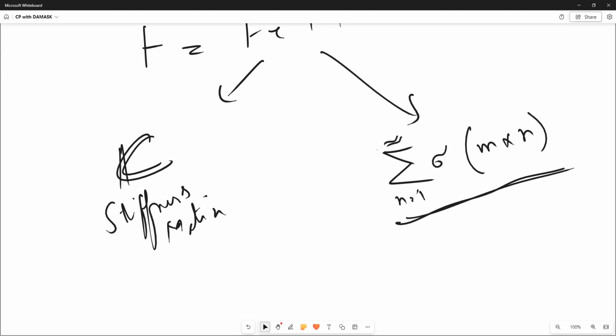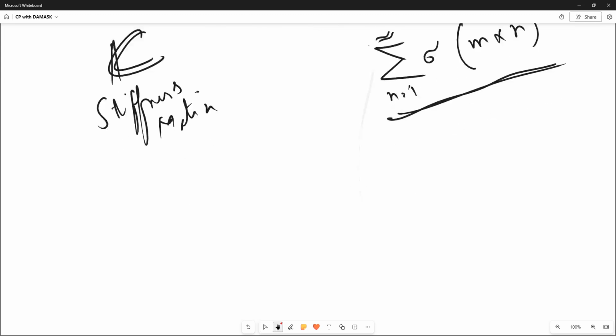And this is basically what we are trying to do, run or simulate using any crystal plasticity software. Here we are taking the example of, for example, DAMASK. You can use Abaqus with your own subroutine. So you can define the flow rules and then you can use Abaqus. There are other crystal plasticity models available out there. People have written their own scripts and models, and they are also using them for any of such simulations. So the basic idea or understanding is this, right? To simulate that,